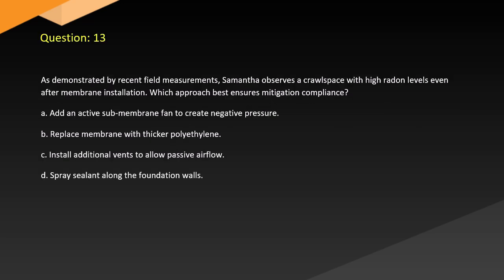Question 13. As demonstrated by recent field measurements, Samantha observes a crawl space with high radon levels even after membrane installation. Which approach best ensures mitigation compliance? A. Add an active submembrane fan to create negative pressure. B. Replace membrane with thicker polyethylene. C. Install additional vents to allow passive airflow. D. Spray sealant along the foundation walls.